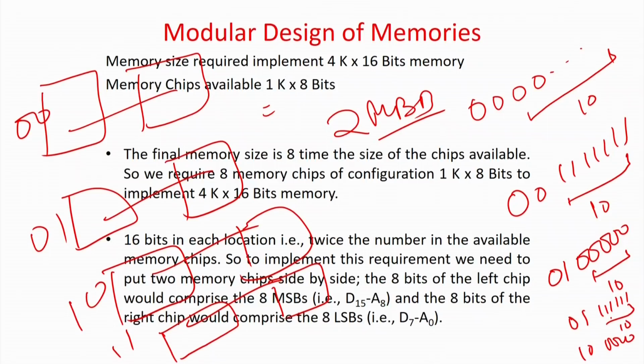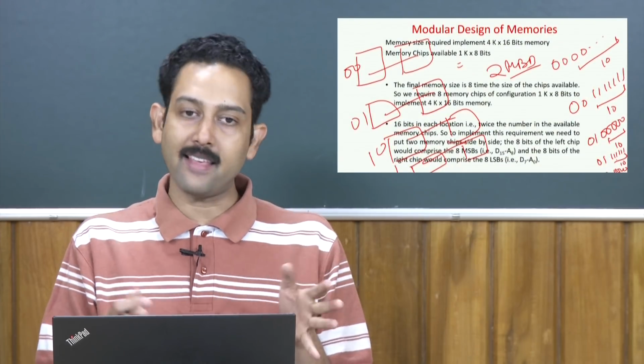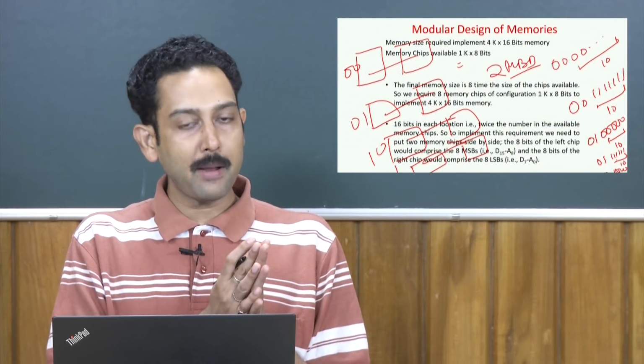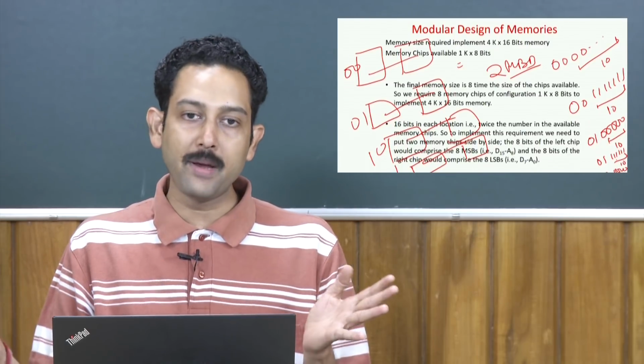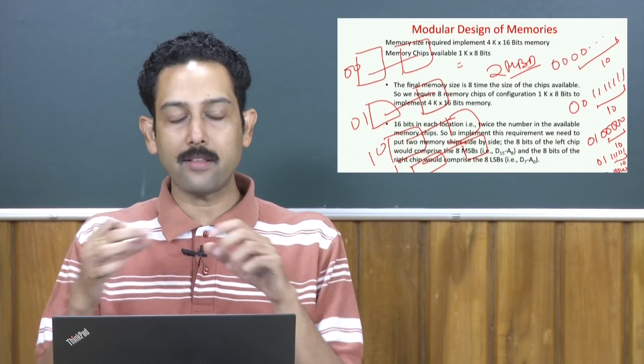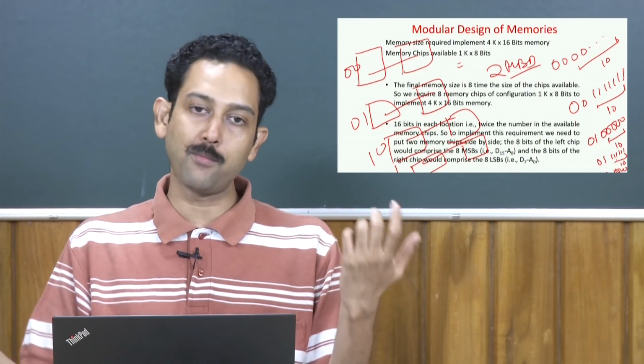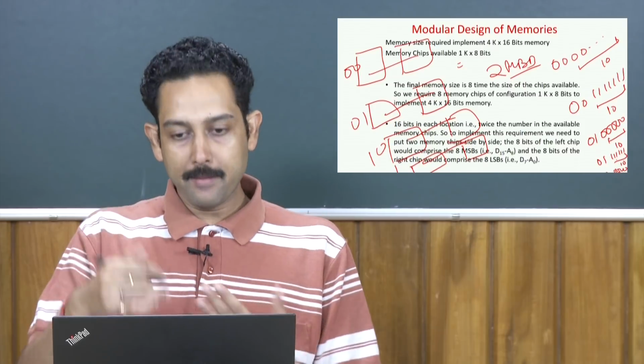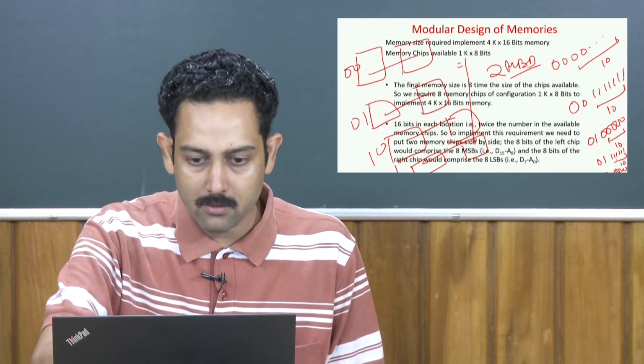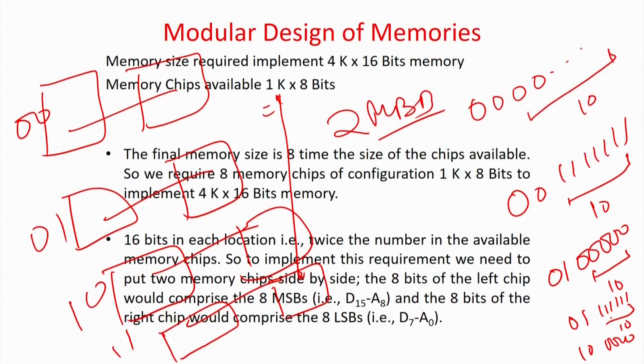So, if you are given a byte addressable memory and you have blocks of size 8 bits, 1 is enough. If you have byte addressable memory blocks and you want 32 bits as the word size, then you need 8 into 4, so 4 memory blocks have to be put in series, and then depending on the size you multiply the rows in that manner.